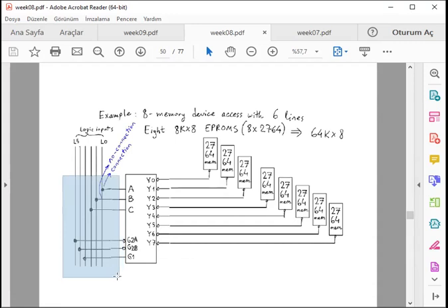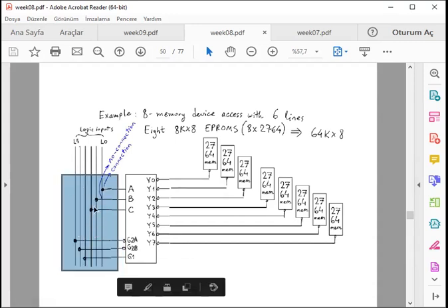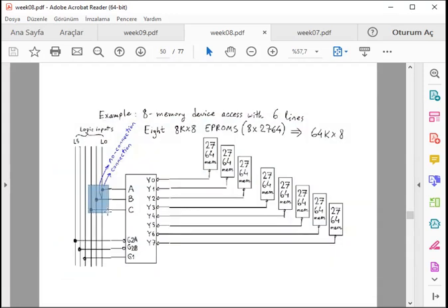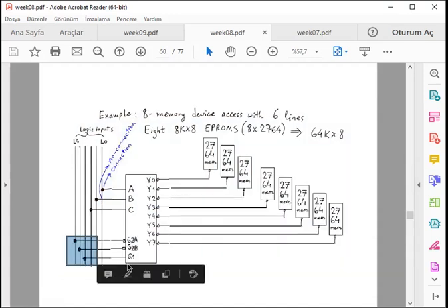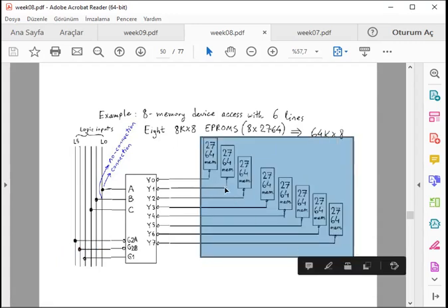So we can connect this circuit to a group of address lines as well. Usually the least significant 3 bits are connected to selection pins, and some other pins are connected to the enable pins to define a certain address to activate this, to utilize 8 identical memory parts, like 2764.